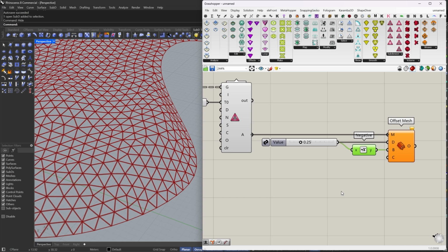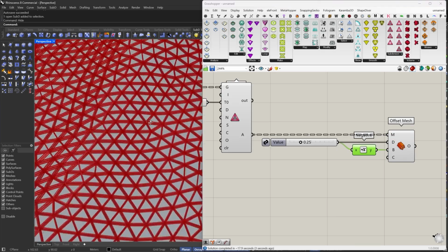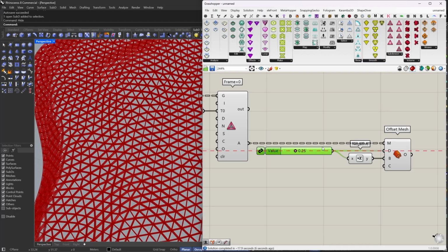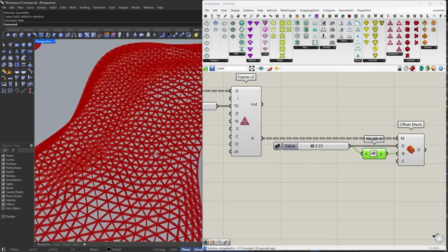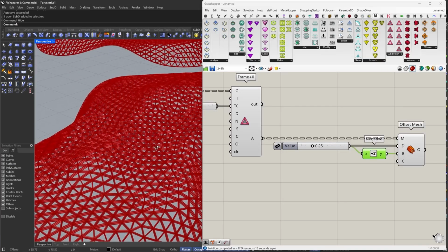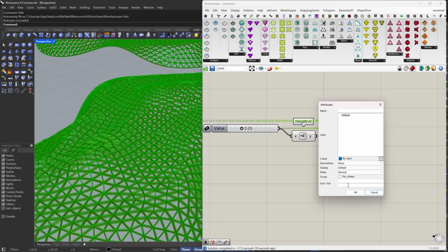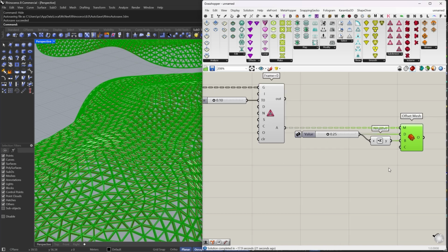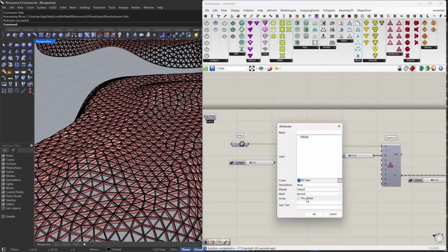And right now you can see that it's taking a little bit of time to process, and this is important because if you increase the meshes more than that, yes, you will get a defined topology, but every step after that is going to take a lot of time, and also it's going to be unnecessarily heavy work for your computer. So right now you can just bake this and say yes, okay, and I'm going to hide all of this and just bake this and yes and okay.